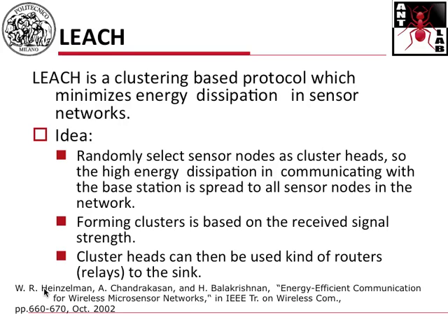And these cluster heads, if they're fixed over time, will be the first ones to deplete their energy. On the other hand, if you change clusters over time, you're changing cluster heads over time, so you are forcing all the nodes to share the energy burden for processing, computation, and transmission, such that you prolong the network lifetime.